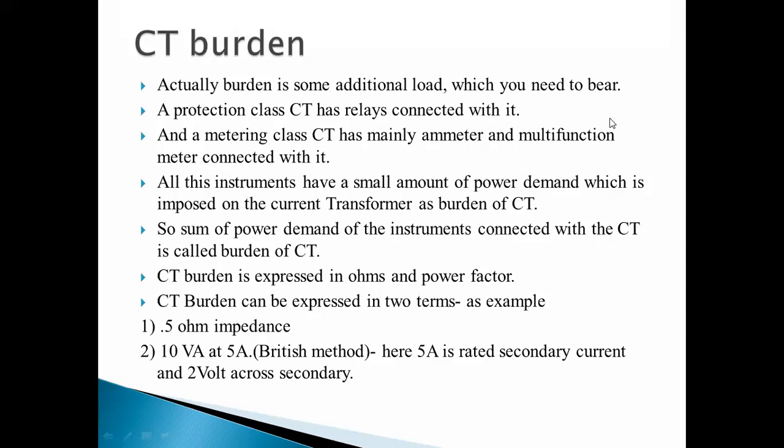So what happens for the current transformers? Sometimes the extra load they have to bear, and that is nothing but the CT burden, and this burden is measured in volt ampere. So it is mainly in point only. Here one example is given, 10 volt ampere at 5 ampere.